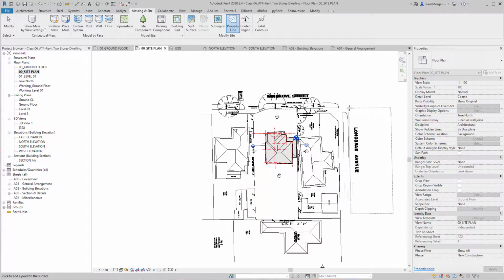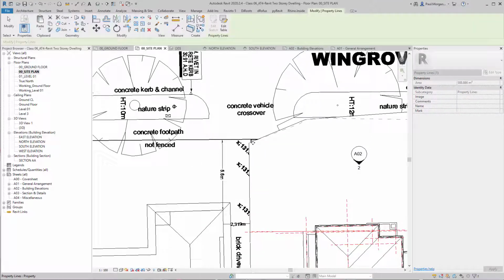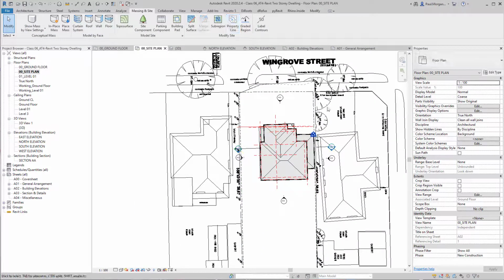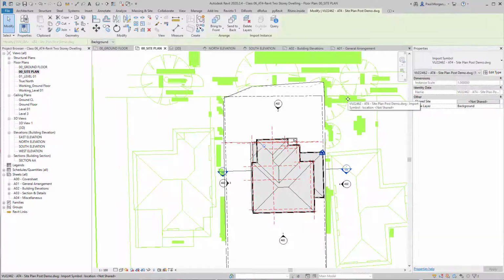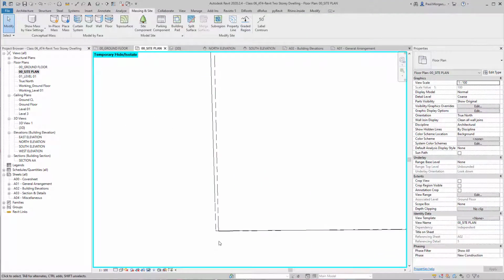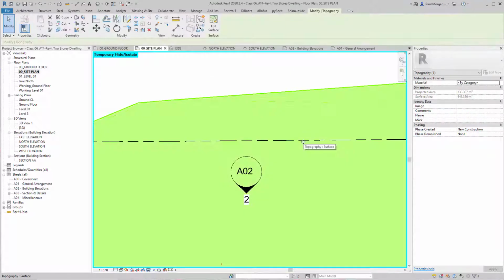And you can see I'm holding that property boundary, and I can place that in a certain location. So I find the corner of that property, I go there, and then I've got my title boundary complete. So you'll see there it is over the top of my drawing. If I just hide the CAD file for a second, it goes to show how it's sitting over the top of our topography, that is actually our title boundary for the property.